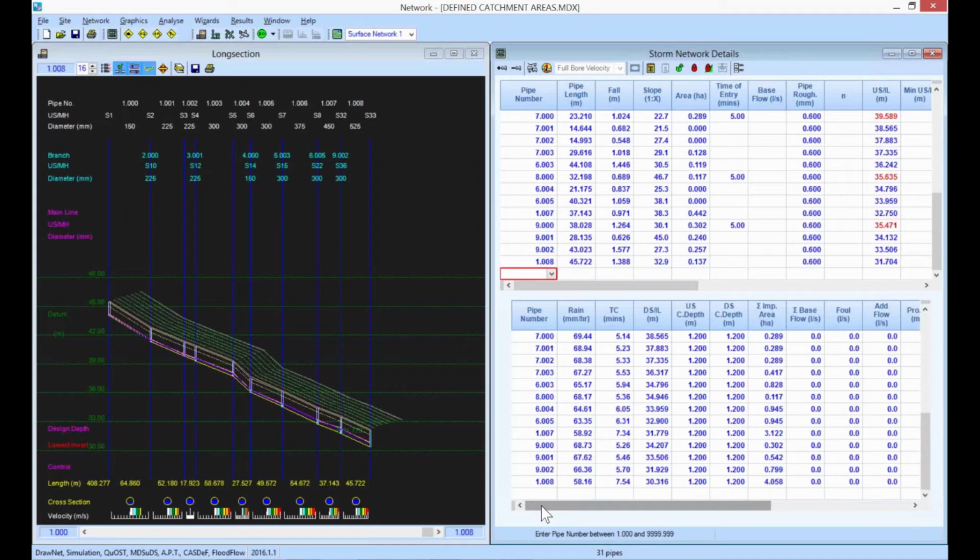So to me as an engineer, this would really be a great driving force to indicate the need to stop that flow further up the system and implement a SUDS and source control style approach, trying to provide the attenuation and slowing down of the flow upstream in the network. Now, unfortunately, the needs of the client are overriding my desire to do SUDS in this case. So I've been told, no, traditional drainage design it is, in you go, crack on. So this is posing a number of problems for me.